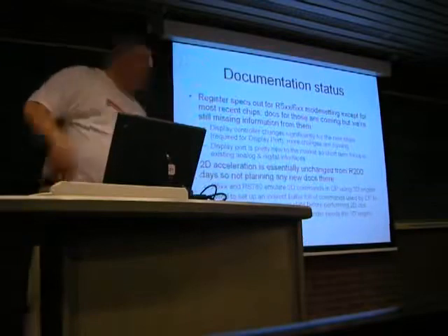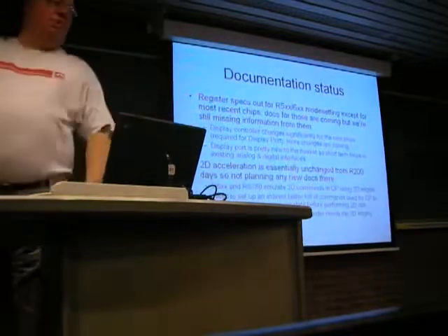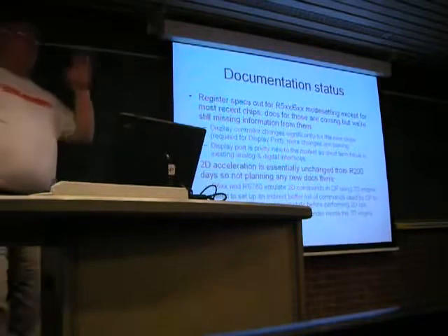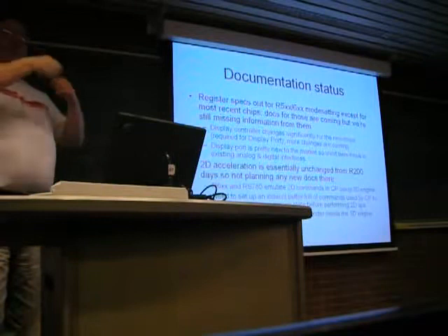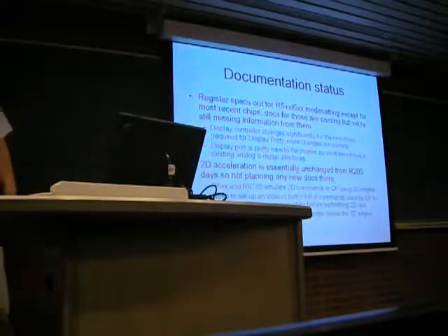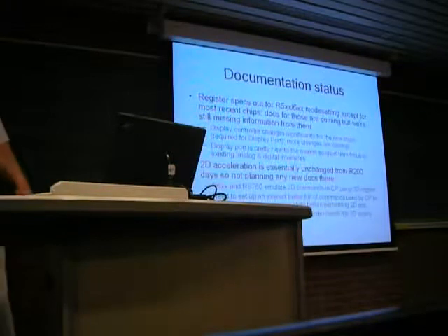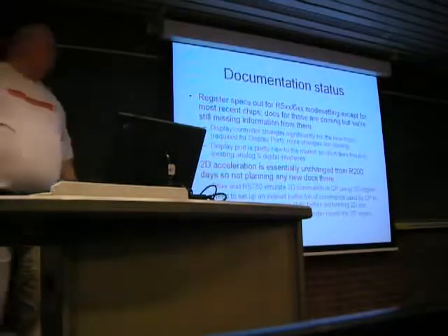Starting with the R6XX parts, we actually took out the 2D engine. So there's historically been 2 ways to program the 2D engine. One is MMIO by punching registers to make it do things, and one is through the command processor where you put in command packets, the chip DMAs them up, and picks them apart and executes them.